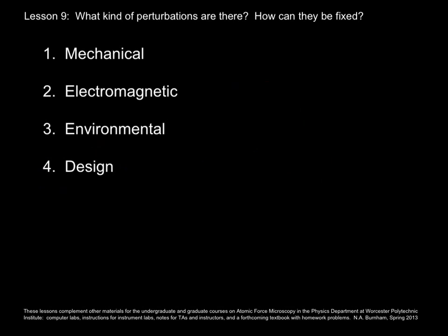In summary then, there are three types of perturbations about which you can make some modifications and maybe help your imaging. And about 3 times a year, I schedule some time to go down into my lab and check for all these types of perturbations, tighten loose parts to ward off mechanical vibrations, check that everything is grounded, make sure my air filters are clean, etc., etc.